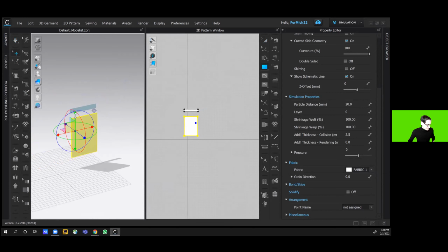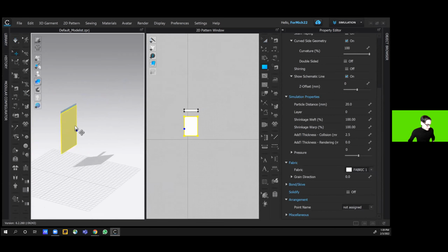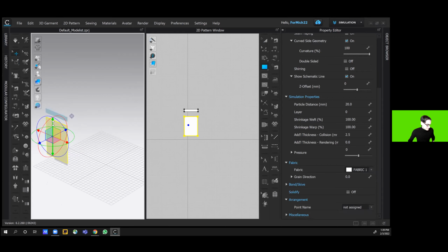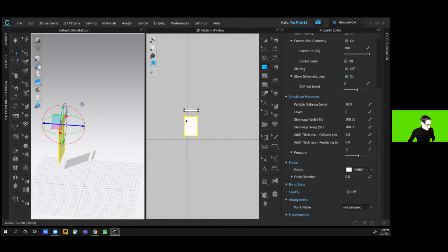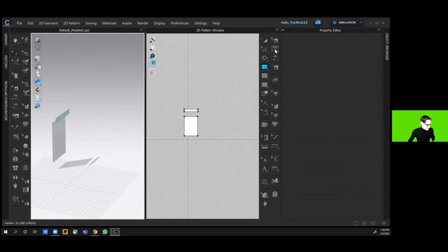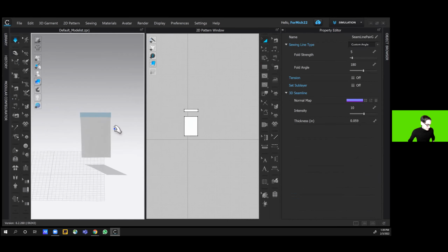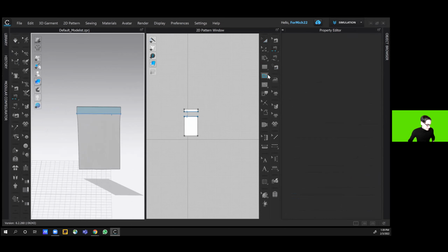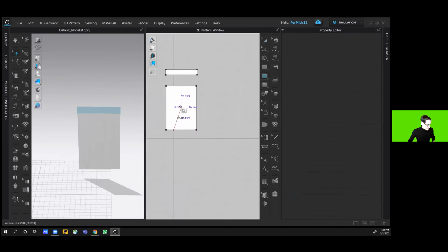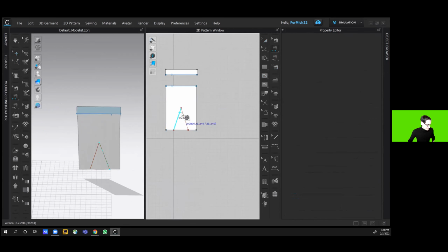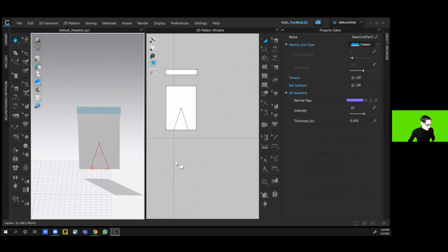And what that is, you're essentially just making a V, and then you're sewing that V so that on one side the distance is shorter than it was before. Sew these together again. Great. And then in the 2D viewport, I will use this command of doing internal polylines, and I'm just going to draw a V. Double click to end it. Use the sewing the segment again. Sew those together. Boom.